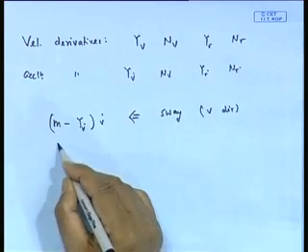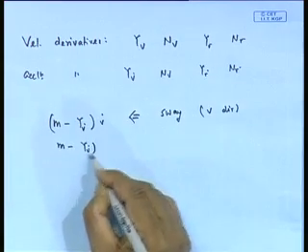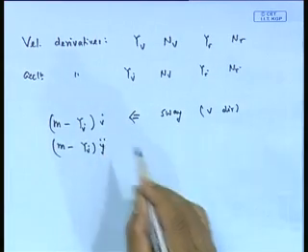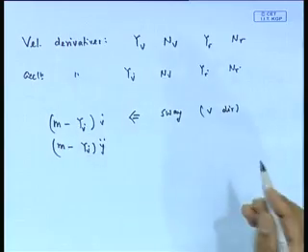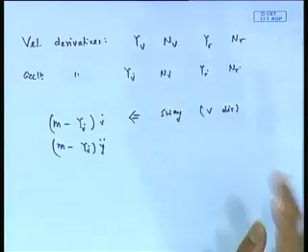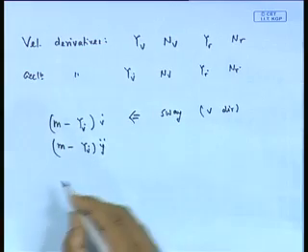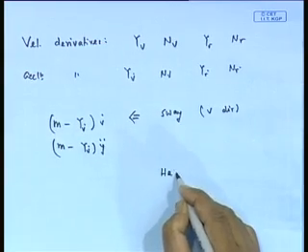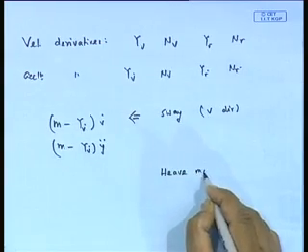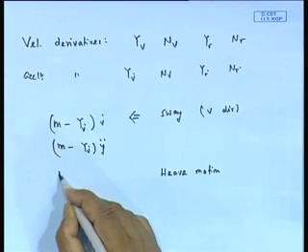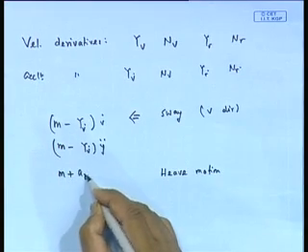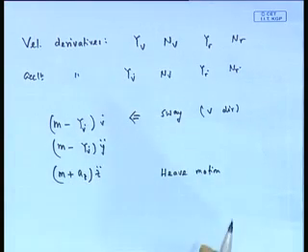So, essentially this is m minus y v dot, into this is y double dot, because if I call x y z to be displacement, in analogy with that, in heave my inertia force was mass plus added mass into z double dot.